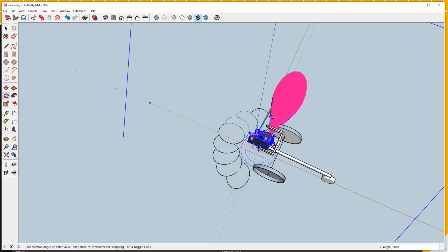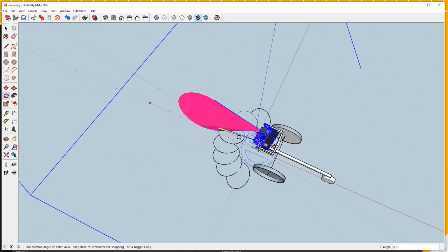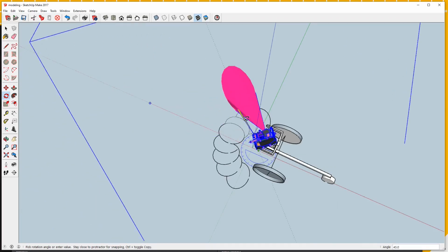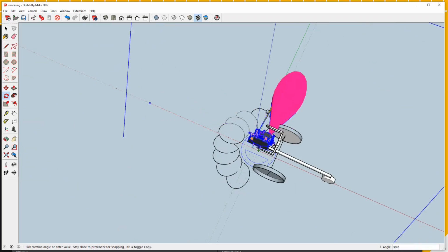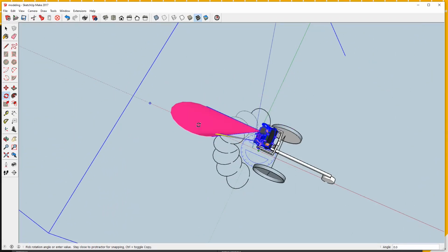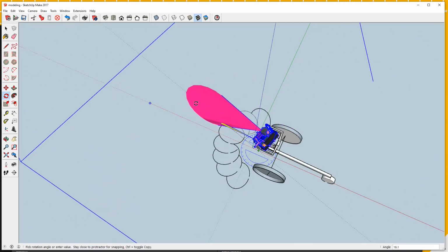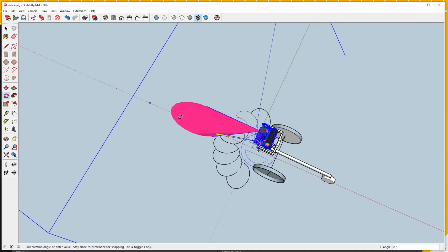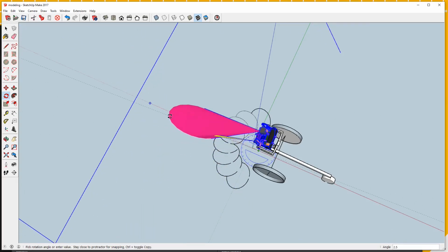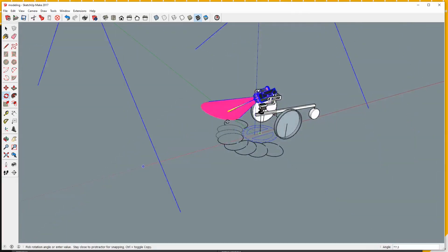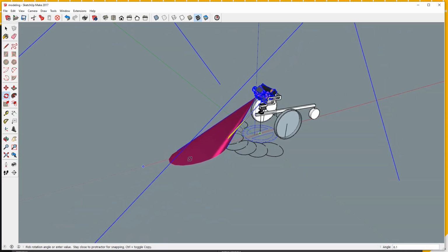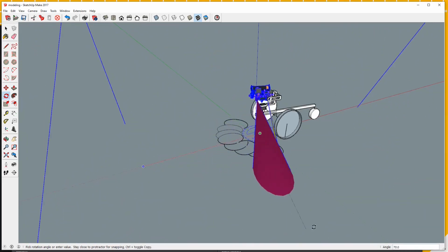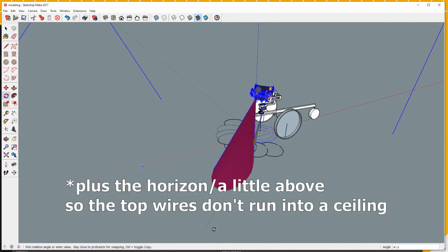And then I'm gonna take a compass in the real world and manually calibrate the servo position externally. That sucks too, but it's a servo, not a stepper with a rotary encoder. I can't really trust it. So yeah, do that. The nice thing is the more it's angled, the more area it covers. So I'll probably just do one more set, and then that'll be the scan coverage that it looks at.